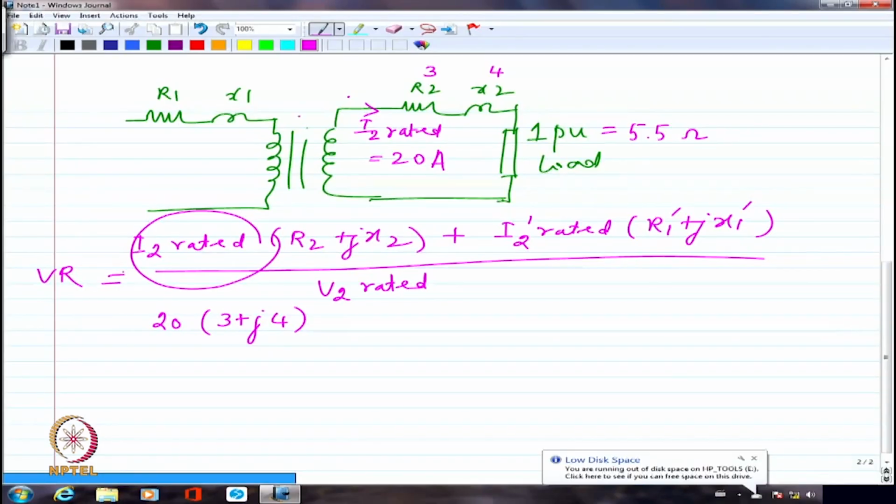So if I am talking about a similar value coming on the primary side, I have to write this as 3 multiplied by 1 by 2 square. Am I right? Or 2 multiplied by 2 square. I am sorry, not 1 by 2 square. I have to erase this. So this will be actually 3 multiplied by 4 because 2 square, right? Because please understand it is 220 by 110 volts transformer.